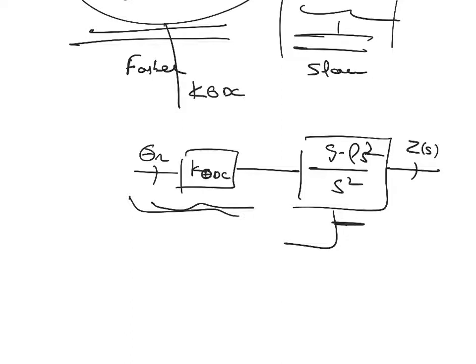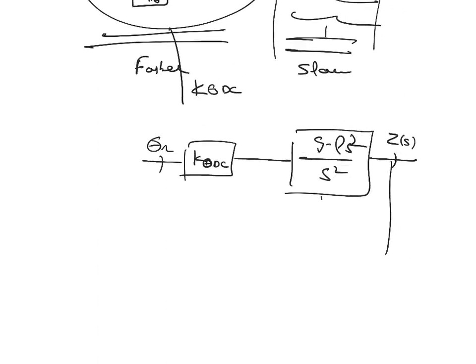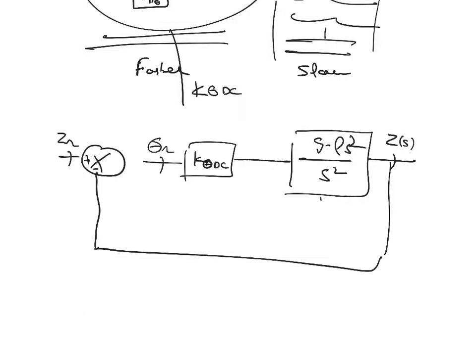So now we can design a PID for this, right? So it will be simple now. For this transfer function, we want to control Z reference now, so we have a Z reference coming, positive, negative, so this Z reference going from here to here gives me an error multiplied by KP Z, right?